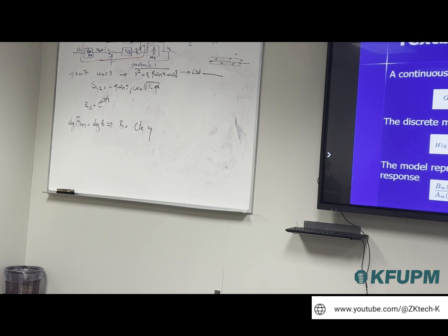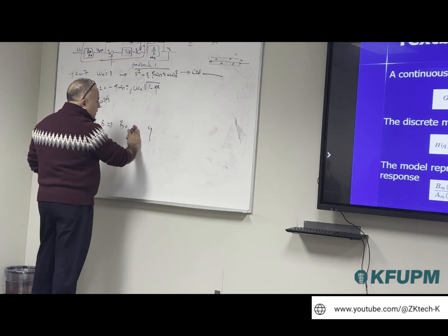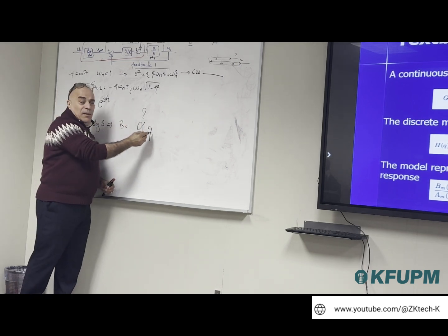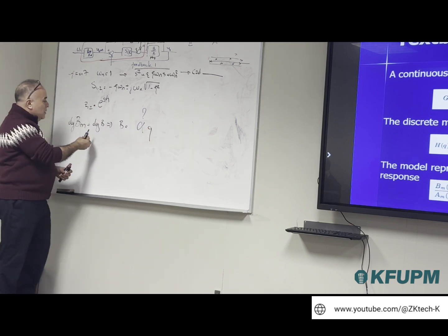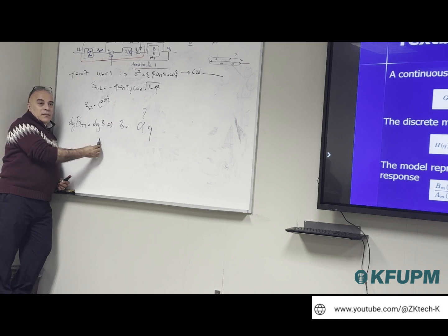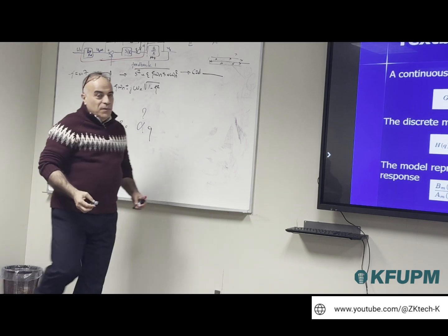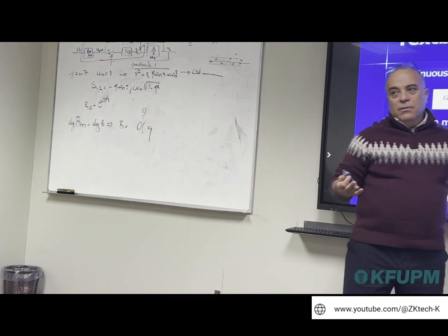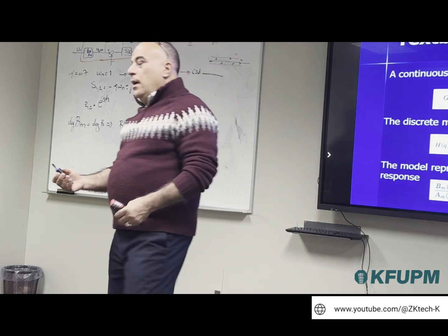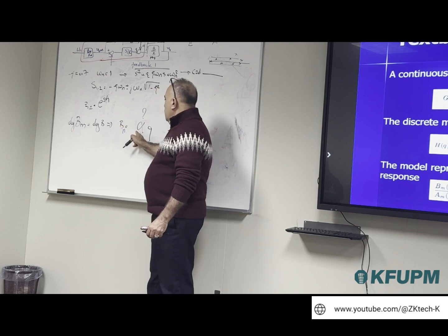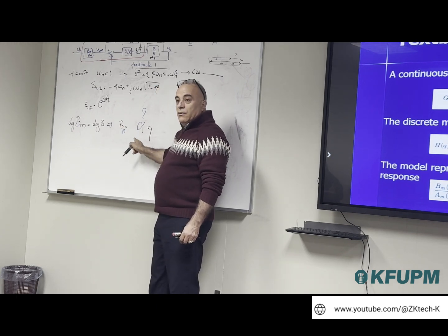Cte is a constant. It's the abbreviation for me for a constant. Alpha times Q. So the question is how to find this alpha. So we can put alpha times q plus alpha 0. Because here, the only condition you have is that degree of Bm is the same as degree of B. Degree of B is coming from the system. My assumption is the system has a degree of 1. So I'm going to use Bm with degree of 1. Now the simplest way is to use Bm, sorry, not B. Bm is equal to alpha times q. How am I going to select alpha?